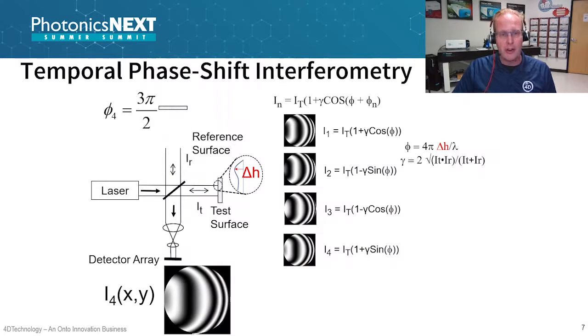And from these fringe patterns, as you likely know, you can use this information to look at the intensities and how they shift through relative phase over a given velocity with respect to each other. And you can use this information, along with the wavelength of the light, to redetermine the structure in terms of a height map with respect to how those fringes change over time.